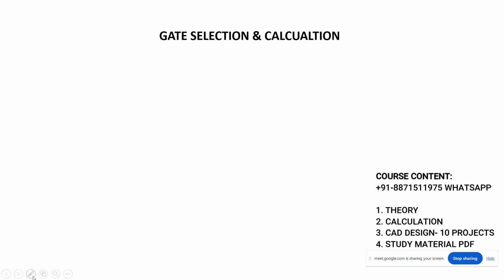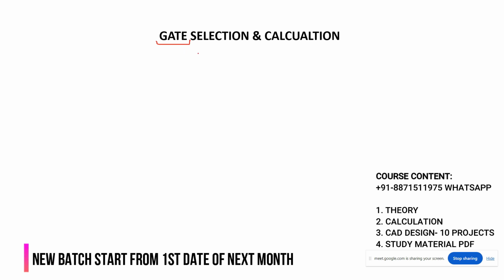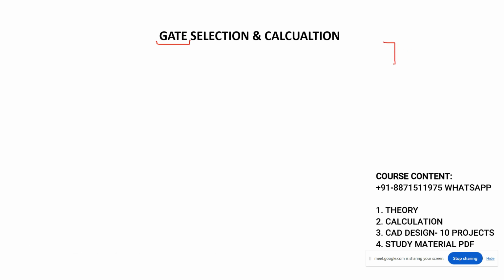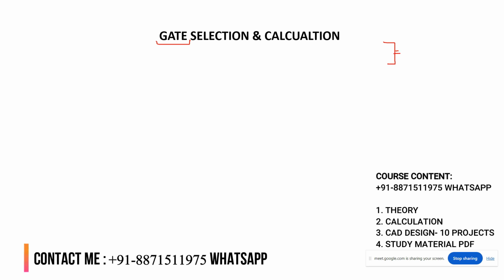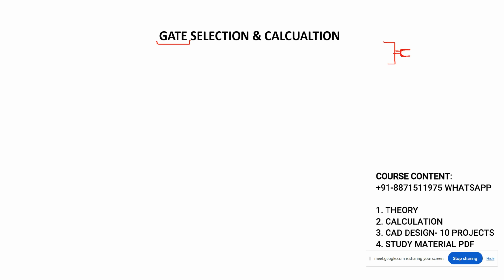What is the main definition of the gate? The passage for the part, so the material can flow. It exists between the component and the sub runner, or the main runner. So basically it will join this runner and the component together. And because of the gate, there is a mark on the component.